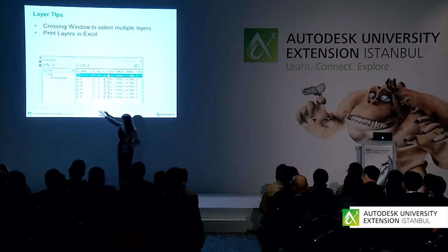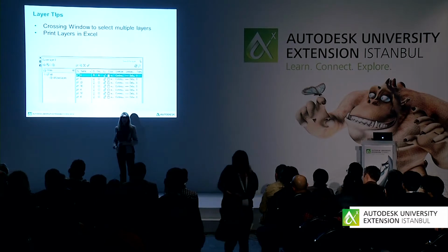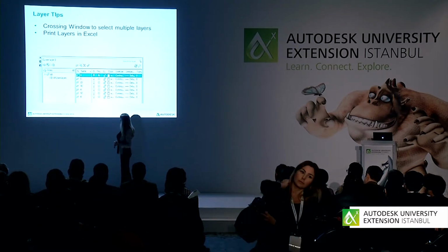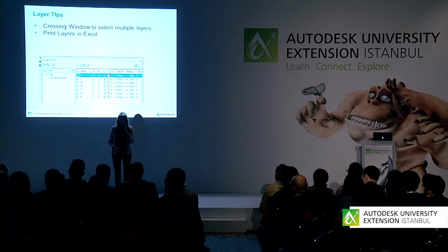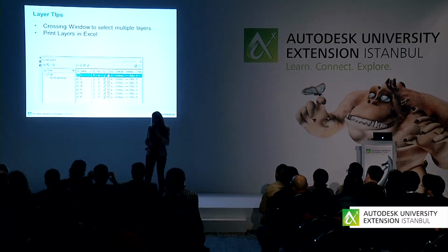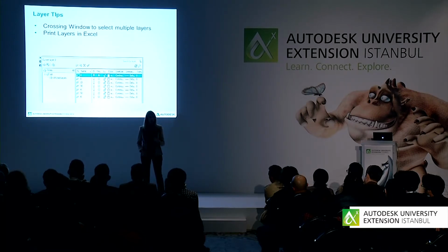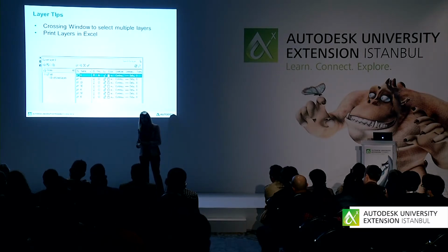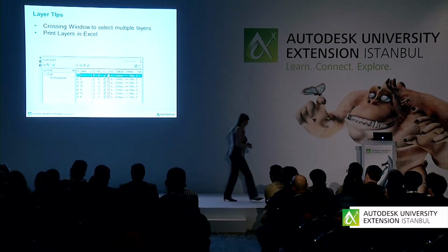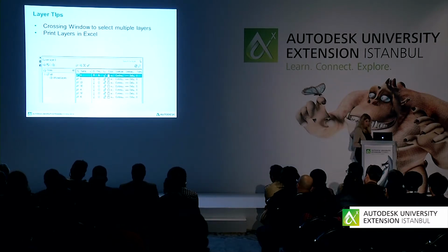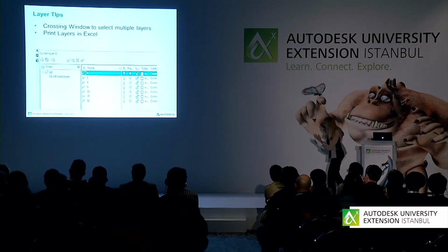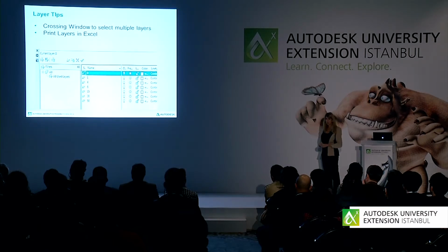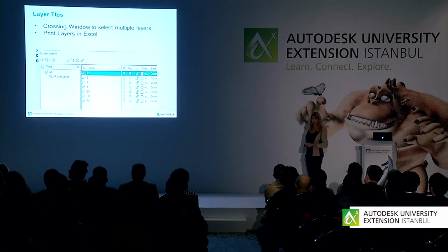But if you gave AutoCAD those numbers, that's the order previously it would have put them in. For example, it takes a look at the very first column, so it would have said 1, and then 15, and then it would have said 30. So far, we're OK. But then it would see a 4, and just take a look at the first column, and then 4 would go next, which is not the way we count. And then it would do 50, and then it would do 6. So with AutoCAD 2014 and 15, now they would show up in a different order. The proper order, the natural order, as they would call it. And there's a system variable called SORTORDER that controls that in case that's not exactly what you wanted.